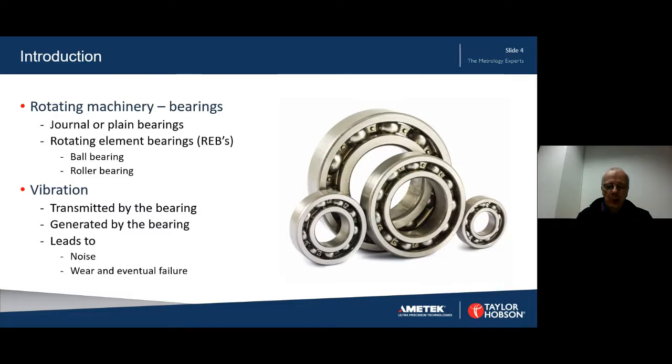For vibrations caused internally to the bearing, the key task is to identify which vibrations are important. Harmonic analysis can be used to identify the frequencies present. To identify the likelihood of a particular frequency causing a problem, for example bearing fatigue, we need to consider the energy in the particular frequency. And that energy is related to the velocity amplitude, and hence the importance of velocity analysis.